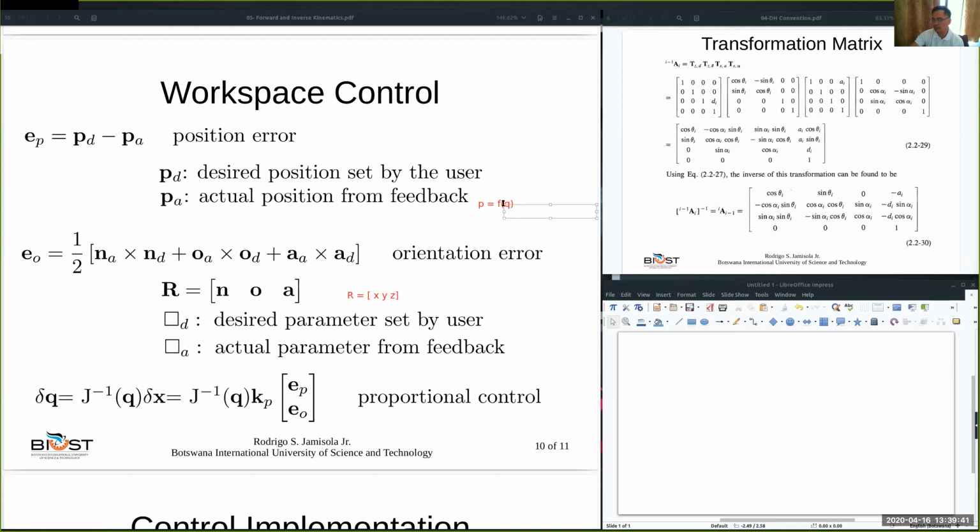So again, by forward kinematics, you can compute the transformation matrix, and then you can get the R. For example, if there are 6 joints, then you have 0A1, and so on, up to 5A6, which gives 0A6. And then you take from there the rotation matrix. That's how you get it.